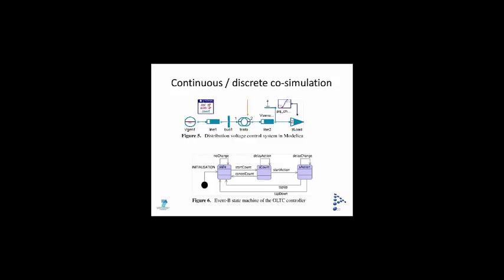And this is what the simulation looks like. So you have, in this case, a local smart grid of a set of houses, which has some sort of voltage generator, and it has a transformer here. And the transformer taps can be altered to make sure that the load matches within the range of 220 or 230 volts. And then you want to develop a controller. So this is an Event-B controller, which is going to control that tap changer.